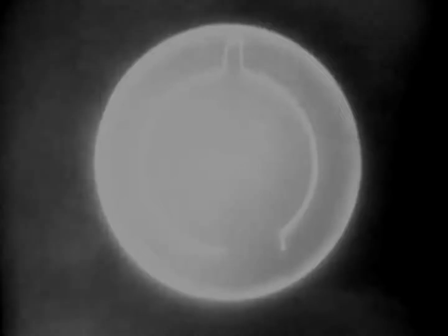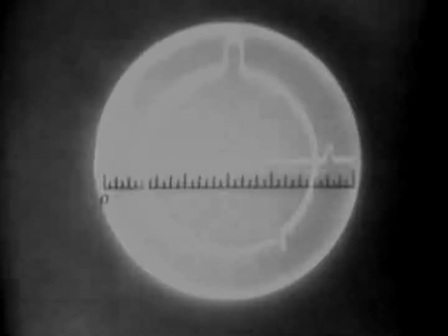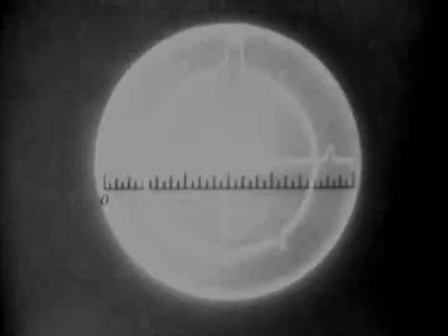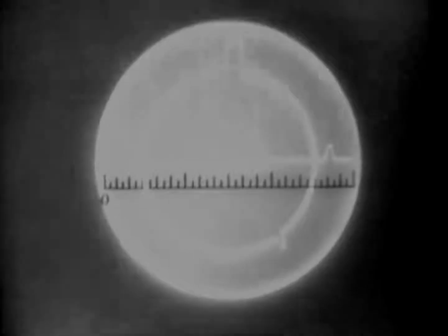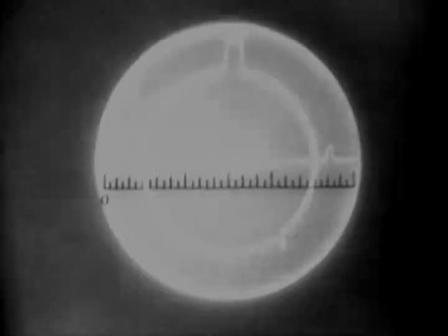This is 0 range. The returning target echo voltage is also applied to the deflecting rod, and another smaller pip will be formed somewhere on the circumference of the circle. As you can see, this scope gives us everything an A-scope did: a main bang, a target pip, and a baseline along which you measure range. But because our new baseline is circular, we can make it almost 3 times as long without increasing the size of the tube, thereby giving us a more precise means of measuring range.